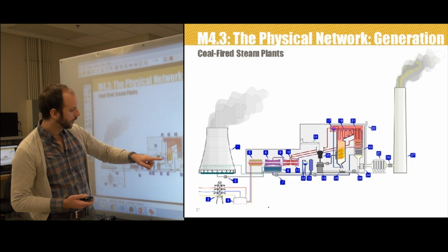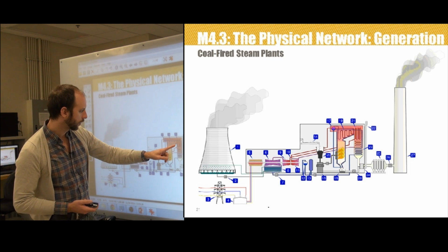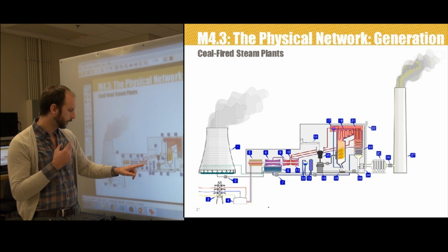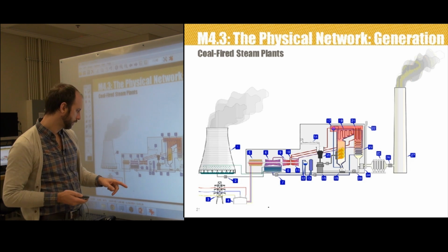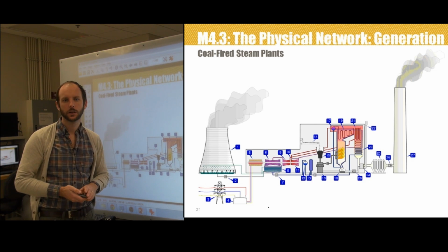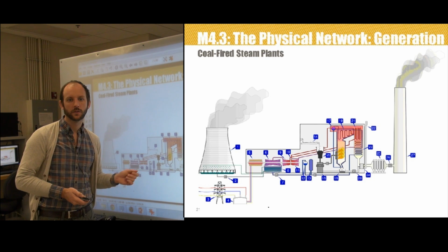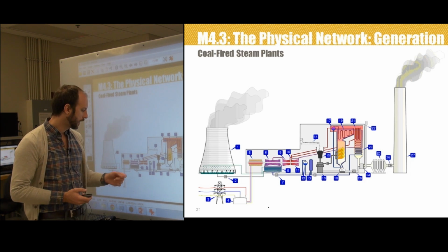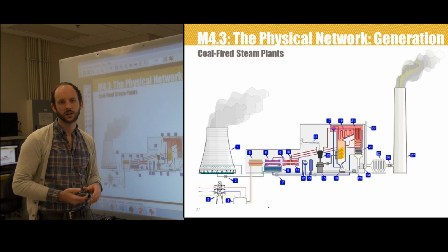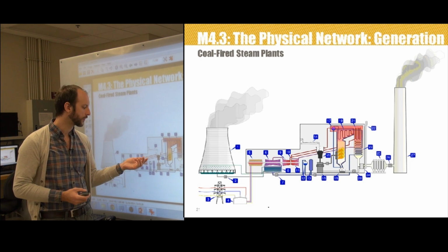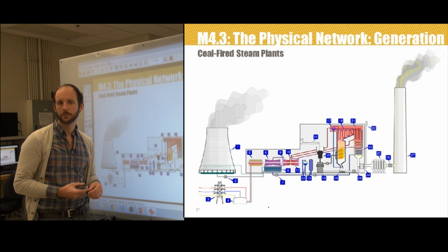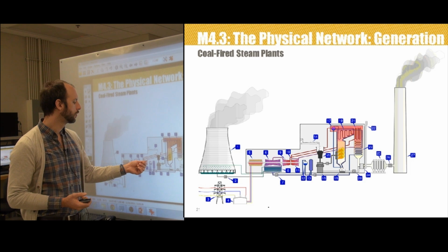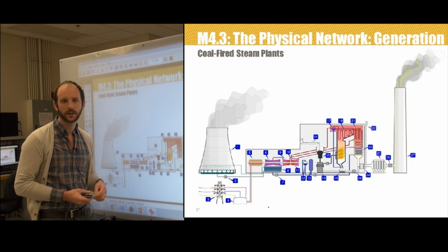The steam then, you may see, goes through this cycle and is pumped down here to number 11, which is called the high pressure turbine. This is the first of a three-stage turbine process here, turbine number 1. So 10 is actually the steam governor valve, which allows you to control the flow of this high pressure steam into the turbine. It allows manual control of the turbine and also automatic set point following. So it's actually how the output of the generator is controlled, by this steam governor valve.